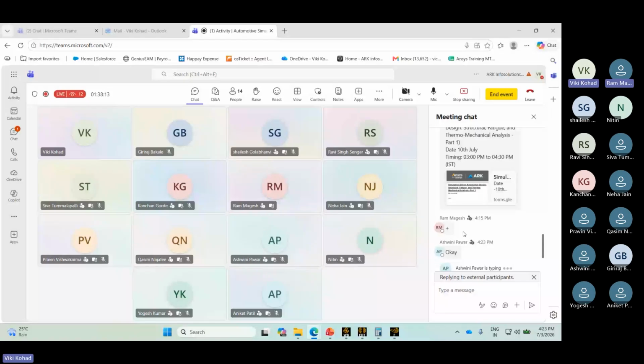Whenever you use the transient simulation, that time it is necessary, or you can say a recommendation. Whatever the time is mentioned, that time mostly affects the FEA mesh. That's why we recommend that for all transient simulations you give the mesh parameters from your side itself.